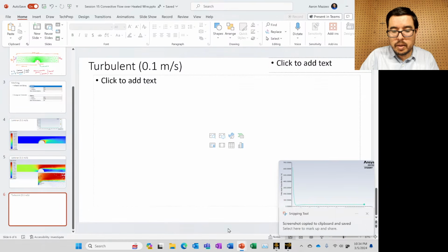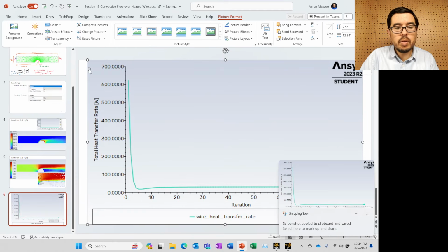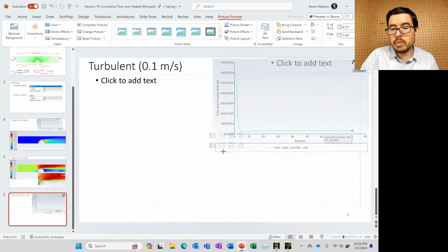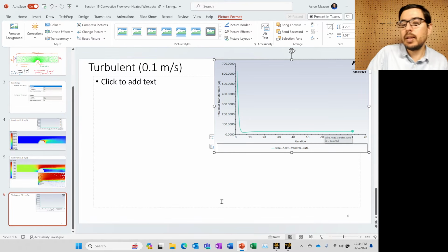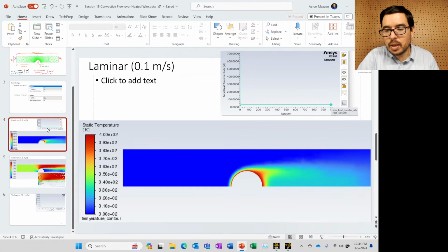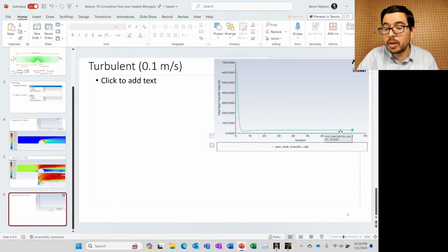And the simulation ran more quickly. It was using turbulent, and that may be an indicator that we should have had turbulence involved earlier. And we have this circulation, so that's another indicator that maybe using K omega is more representative of what's actually happening. But as you'll see, the differences in the outcomes may not be so significant. It took 980 iterations, or 1,000 iterations, to get us to 30.95, and now we're at 30.94. Not a huge difference in terms of watts.